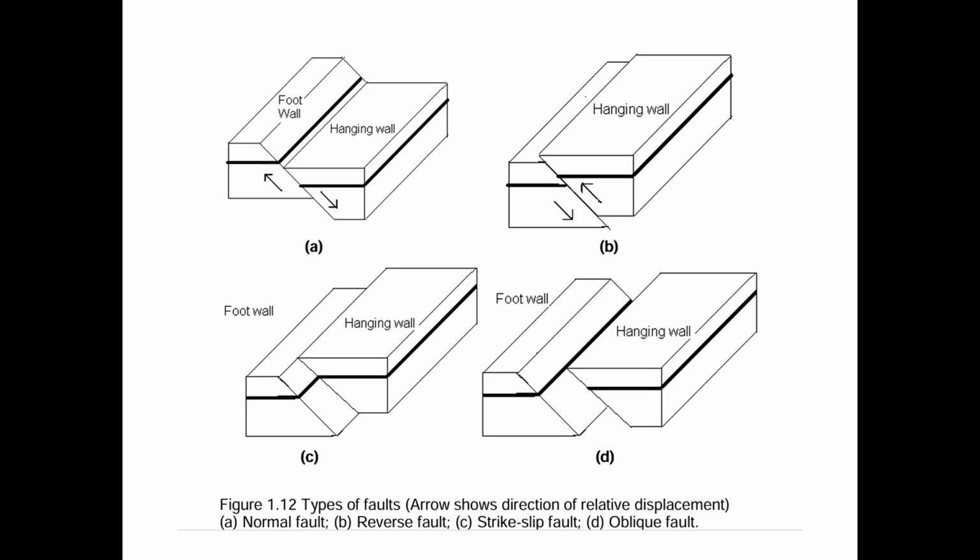Now whatever we have studied in the last two slides, we are going to understand through very simple figures. Here both concepts are covered: classification of the fault as well as hanging wall and footwall. So here you can see this is the hanging wall. In the definition it is called the upper rock surface, but here you see it has moved downward. Why? Because we have shown here A, which means a normal fault. In a normal fault, the hanging wall is moved downward, whereas the footwall is moved upward. Then we call it a normal fault.